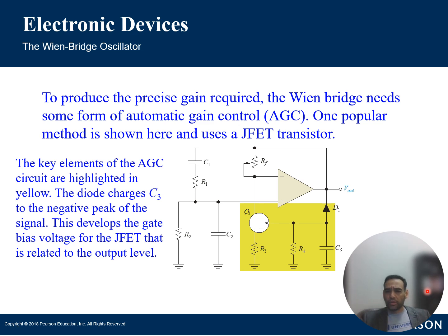You have to do that so you can sustain continuous oscillation from the feedback, right? So it ensures that you have that constant amplitude over that wide range of frequencies. Now we talked about automatic gain control, AGC, and so a little bit more into that, right?